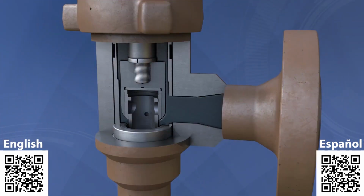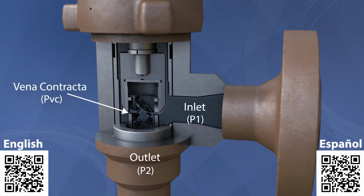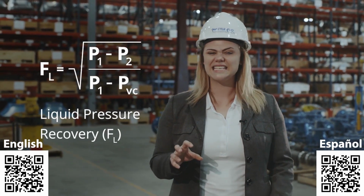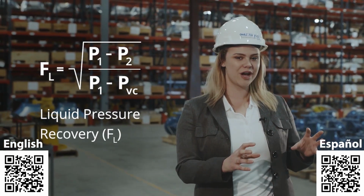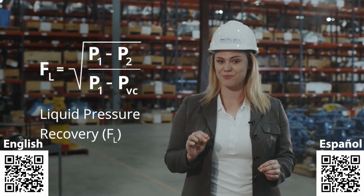In production, only inlet and outlet pressure values are measured. However, inside the valve at the throttling point, the pressure is much lower. This is designated as the vena contracta pressure. That brings us to another important factor of the choke valve selection process, the liquid pressure recovery. This is the ratio between the pressure drop and the difference between the upstream and the vena contracta pressures.